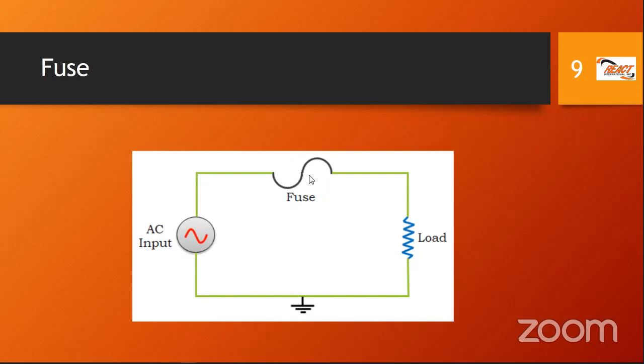So that's the purpose of a fuse as well as a circuit breaker, to protect you in case there's some sort of fault. Meaning that if you only expect 2 amperes or 15 amperes through the circuit and more flows, that suggests a short circuit or something is wrong. And the fuse is there to protect you. So a fuse is a very important component for electrical safety.